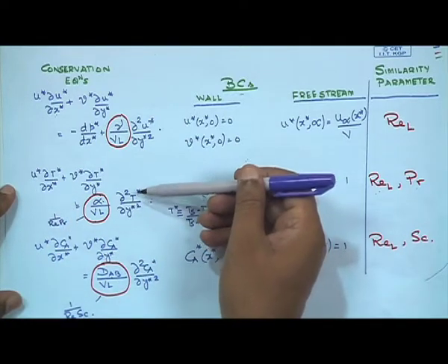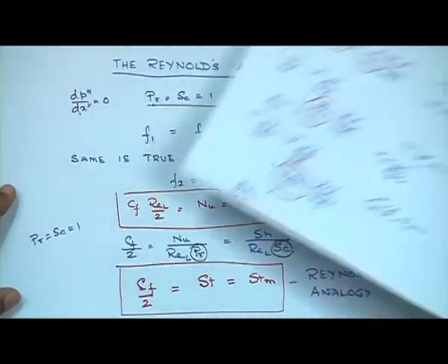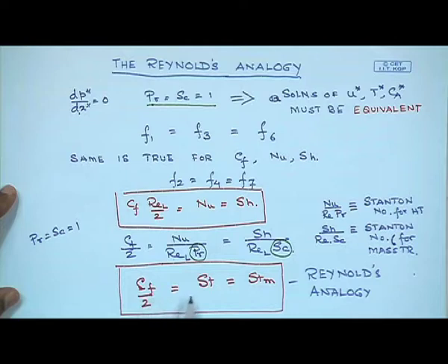So, a simultaneous solution of these two are needed, but we do not have to do that anymore, since we have the Reynolds analogy, which directly relates Nusselt number with the expression of the friction coefficient, either in laminar flow or in turbulent flow. So, an expression for Nusselt number can thus be obtained from the expression of Cf in the various types of flow. So, that is a big advantage, but let us think about the disadvantage now.